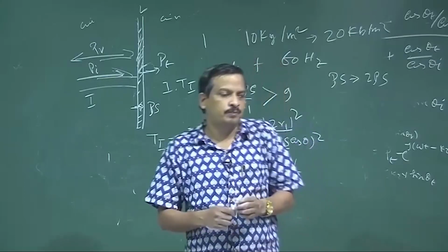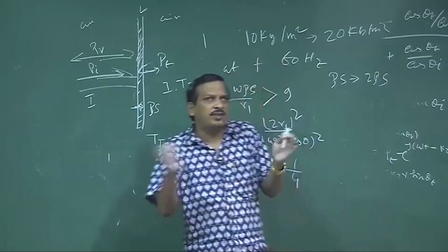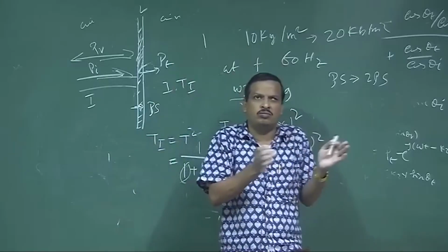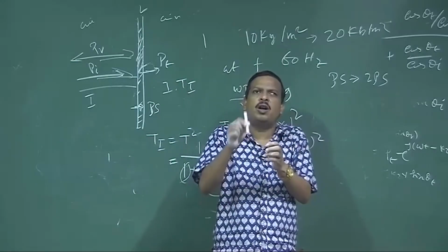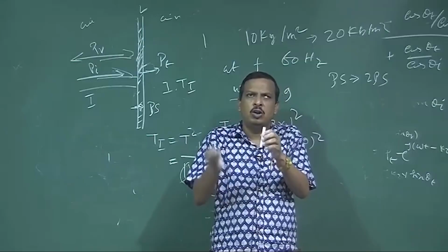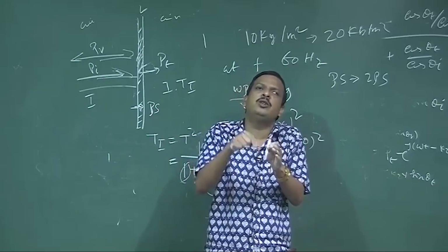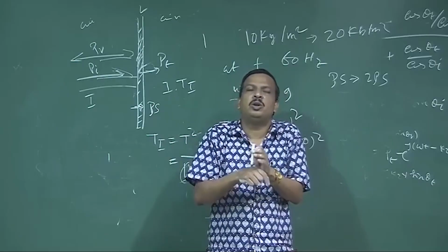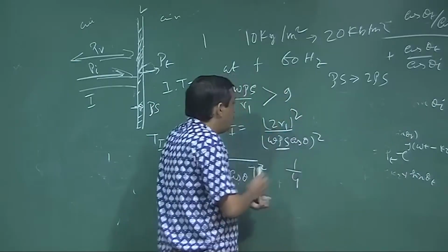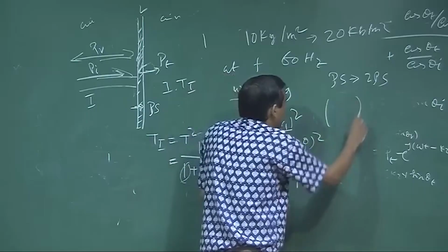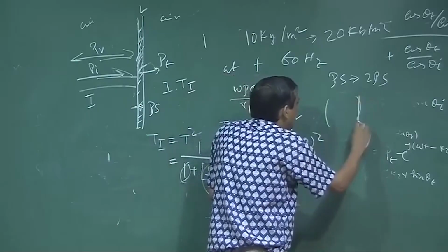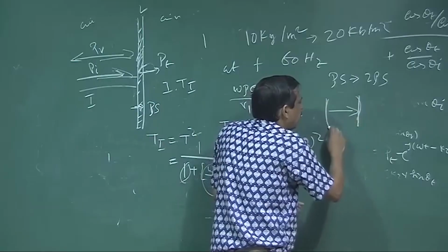Sometimes in acoustic isolation, when we make a door, instead of a solid door, we make a glass door with two glass layers, and in between there will be air. So, the transmission will be reduced. This is the studio, this is a glass door in one layer. So, there will be inverse mass law calculation.